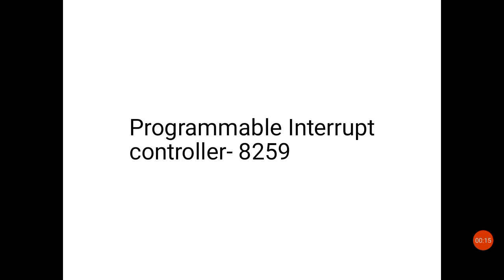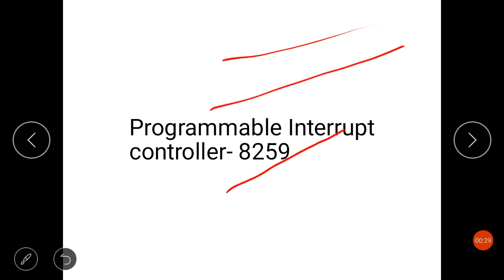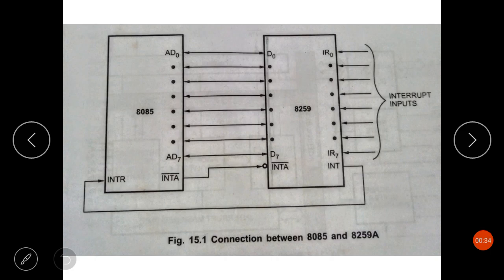As we know, interrupts can be used for a variety of applications, and each of these interrupt applications requires a separate input. Now if we are working with an 8085 microprocessor, we know there are 5 types of interrupts. They are trap, RST 7.5, RST 6.5, RST 5.5 and INTR interrupt inputs. We know this 8085 has 5 interrupt inputs. Now for many applications